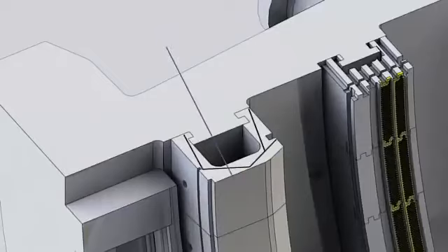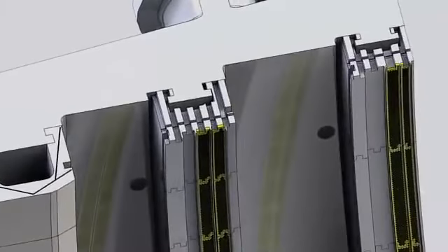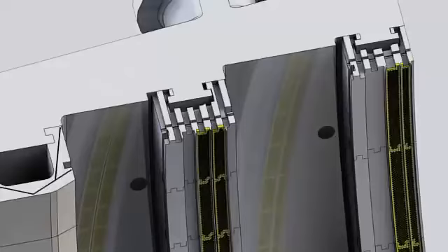The first stage shroud is coated with thermal barrier coating to withstand the extremely high temperatures at this stage. The second and third stage shrouds have teeth that mate with teeth on the tip of the second and third stage buckets. This labyrinth seal minimizes tip leakage. For better tip clearance, a honeycomb seal is integrated on the second and third stage shrouds. This honeycomb is relatively soft material. The cutter teeth on the tip of the second and the third stage buckets open a slot on the honeycomb seal without any material transferred, providing tighter clearances to improve the unit efficiency.